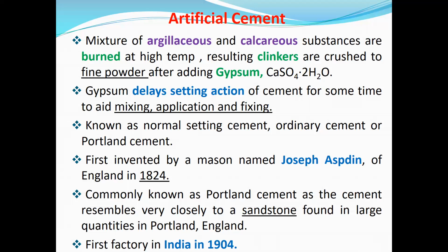So at that time you need to keep the material, if not liquid, in a semi-solid state. So you add gypsum so that the setting action, the change of state, is delayed. The main purpose of adding gypsum is to delay the setting action of cement, so that you have sufficient time, which will help you in mixing, application, and fixing.